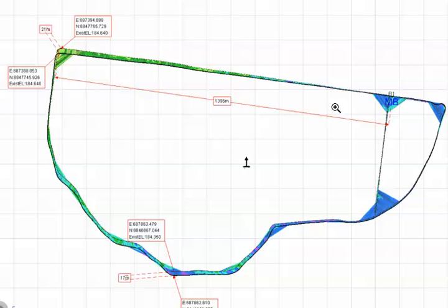So just be aware of this issue. And the easiest solution is to survey with the same system, same type of system that you wish to do the earthworks with.